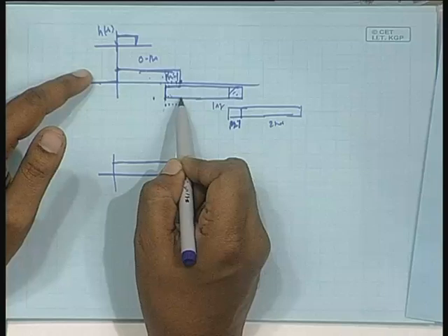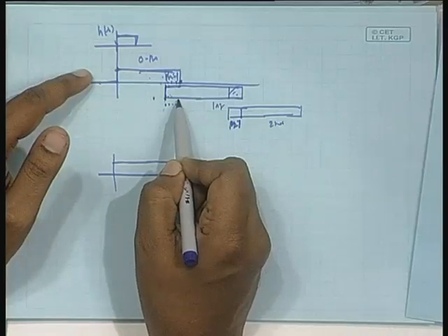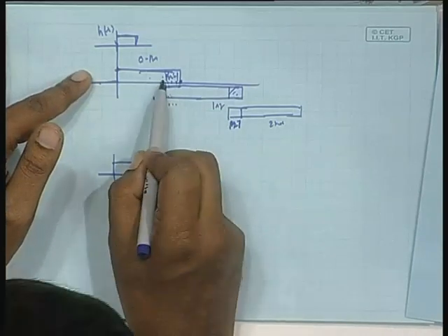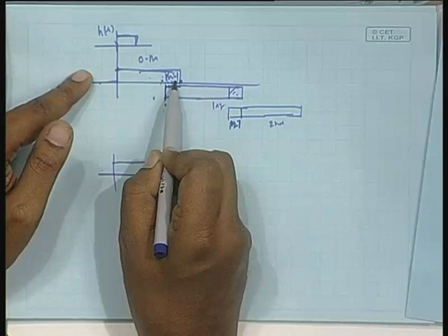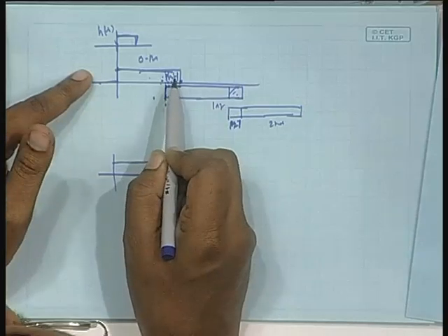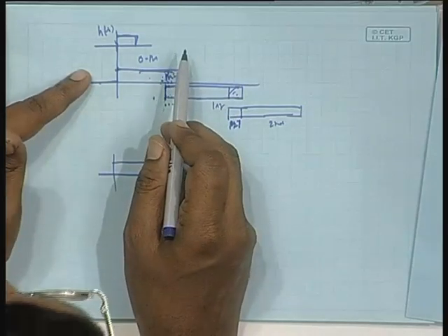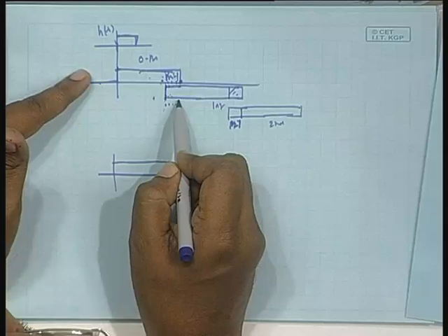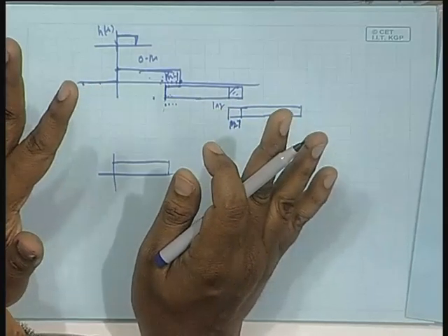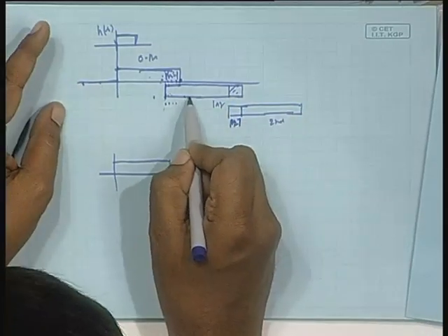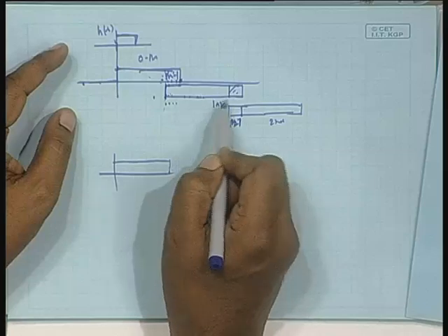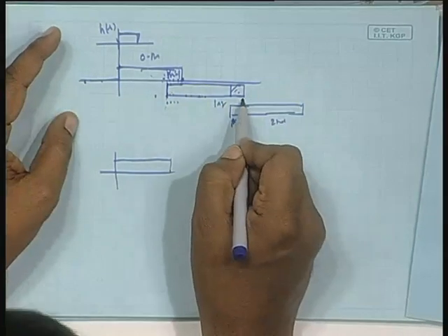So, those outputs I ignore. Who will supply me the output? From the previous block computation I already computed them, I stored them, saved them, that is the overlap and save. So, at these points I get incorrect result, but I ignored. Only from this point onwards I get correct result, I stored them till here.